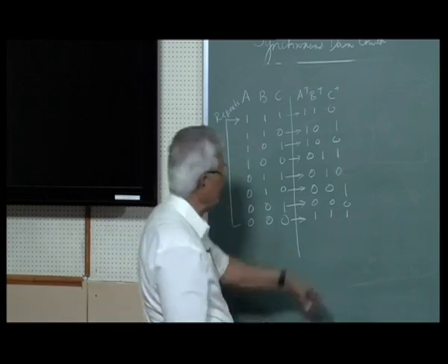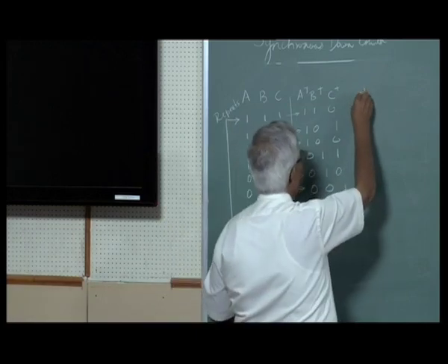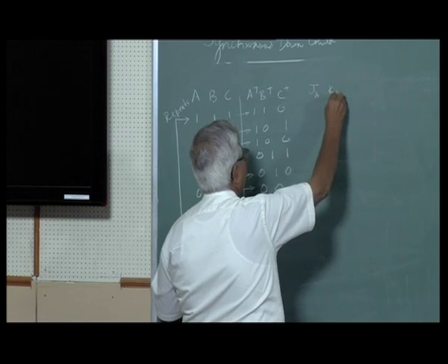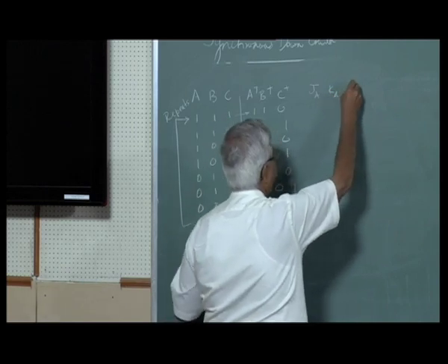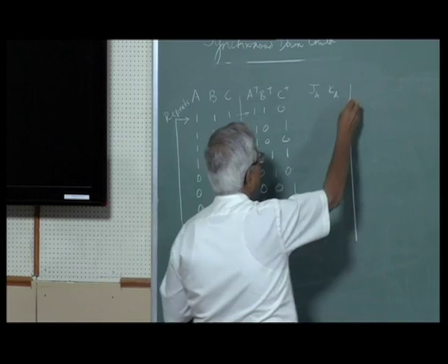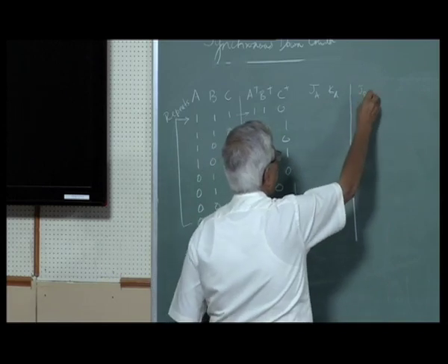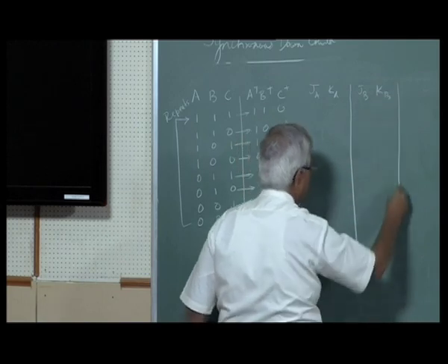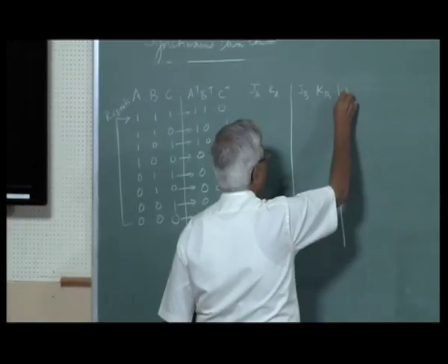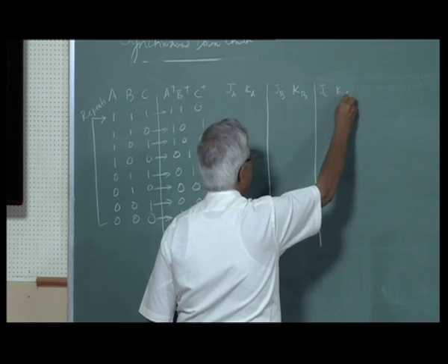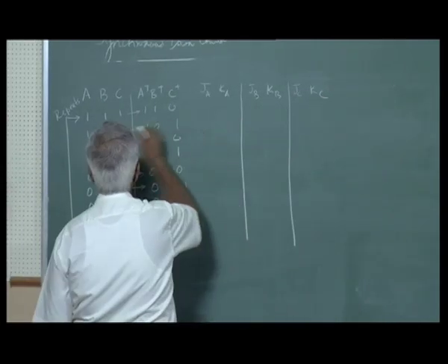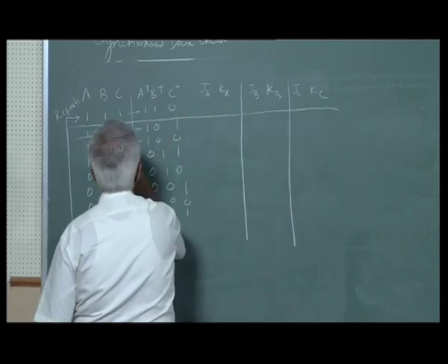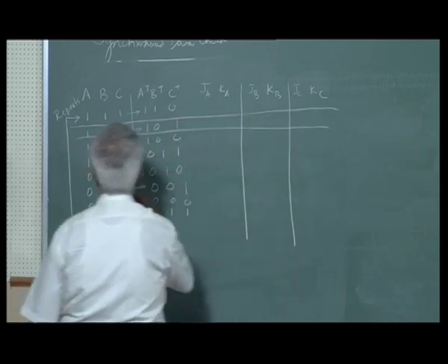Now instead of D flip flops, I am going to use JK flip flops. So I need JA, KA. What will I give as inputs to JK flip flop? For the first flip flop JA, KA, for the second flip flop, I will call it JB, KB as the inputs. Third flip flop, I will call it JC, KC. To make sure that they stay in line, I will put these horizontal lines so that I do not deviate.